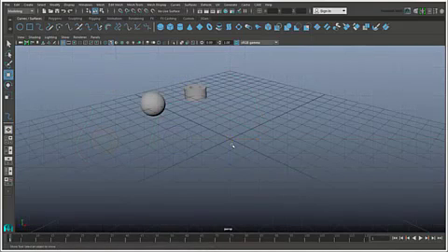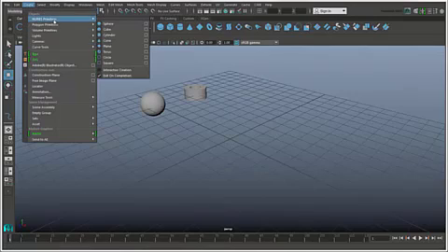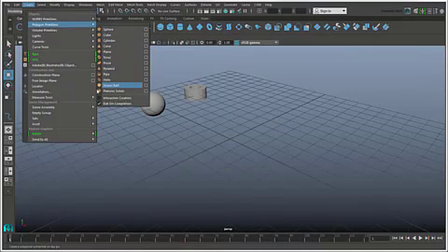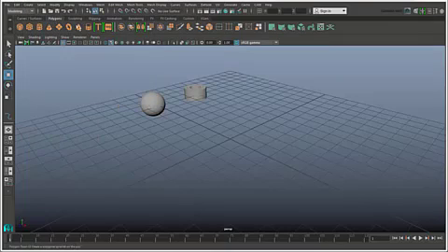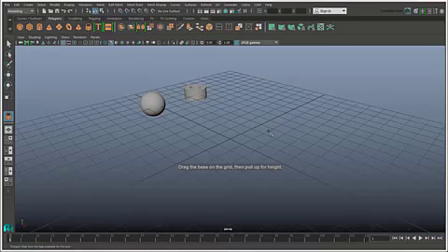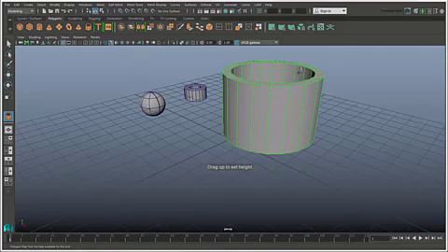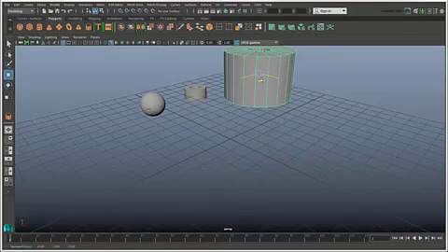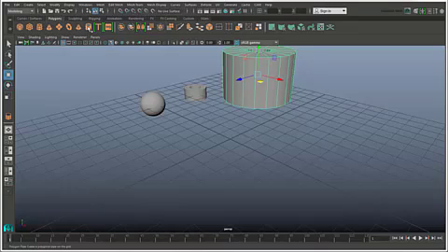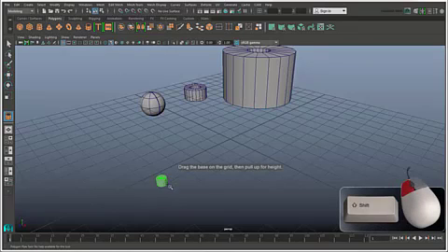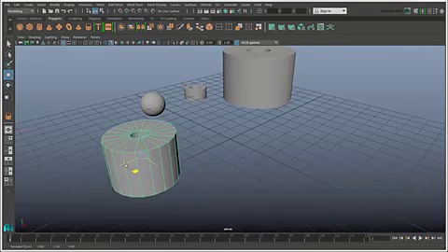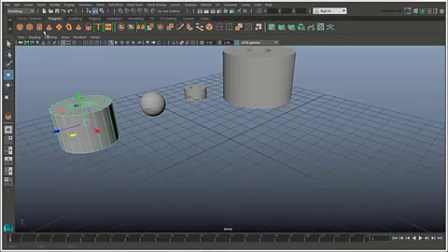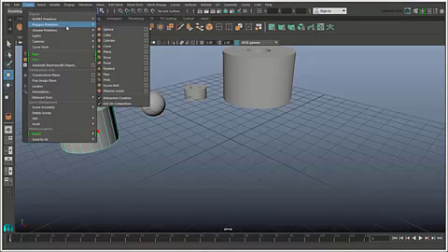If you want to make a custom-sized primitive object, turn on Interactive Creation in the Create Primitives menu. And draw the primitive in the scene wherever you want it, and to whatever size you like. You can also press Shift while dragging to grow the object from its base, which keeps it on the grid. Let's go back to the default mode with no interactive drawing.